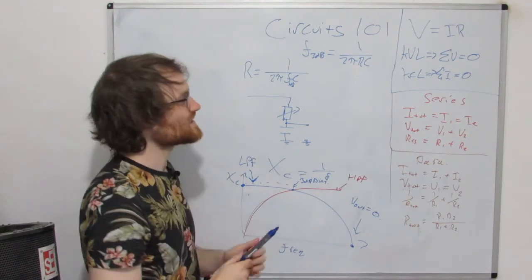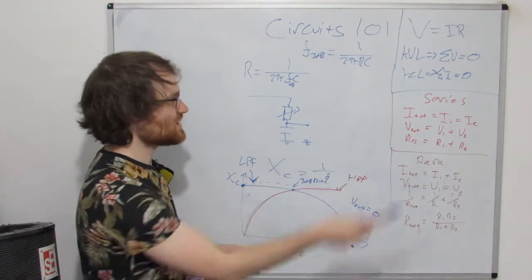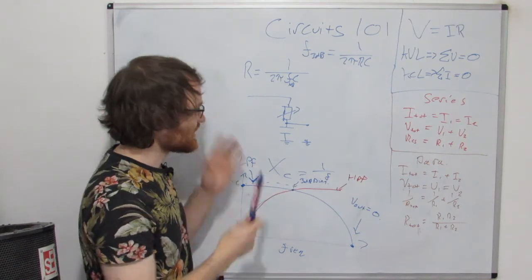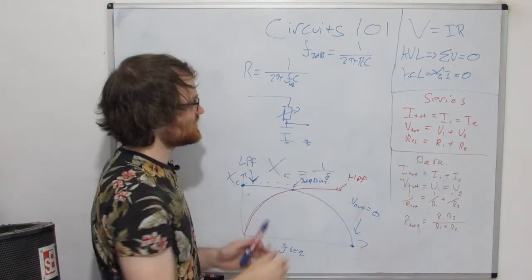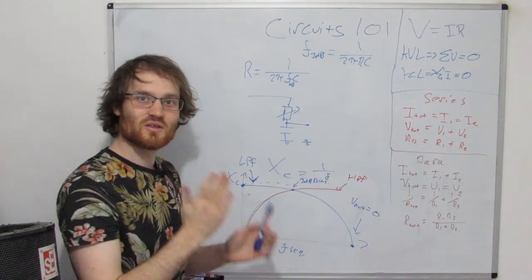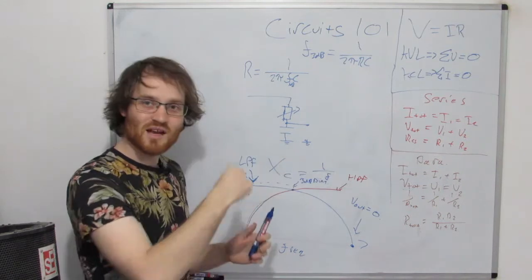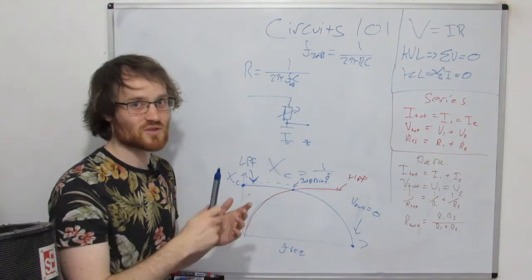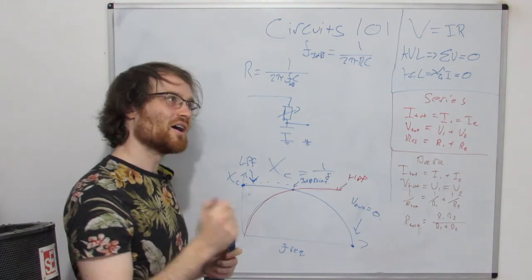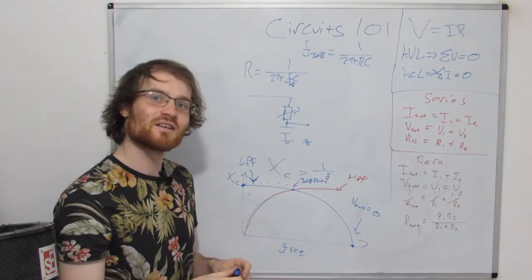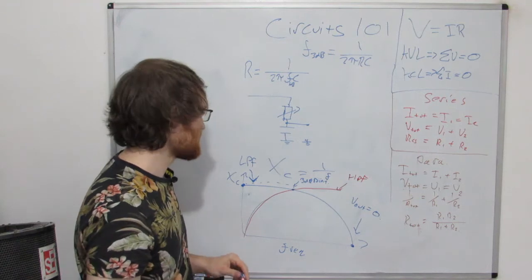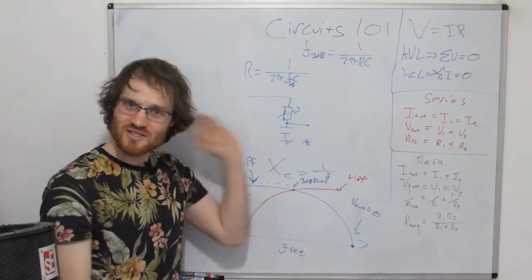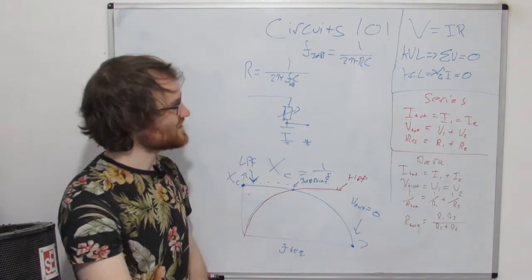And once we've got that, we can put this in our feedback path, and like we were doing before, we can electronically control this filter with resistances. You can either do the routing thing to have an 8-step filter that steps through, or we can move on, which we will do soon, to some more advanced control techniques. So this is a low pass filter. That's the very basics of circuits with resistors and filters and throwing everything in there.